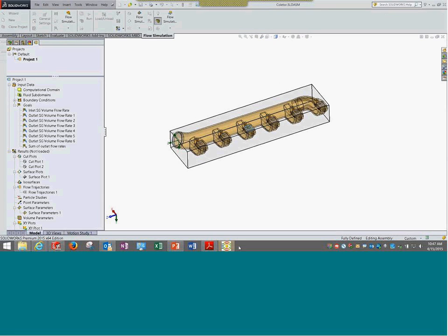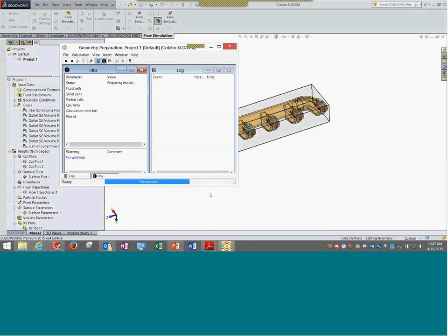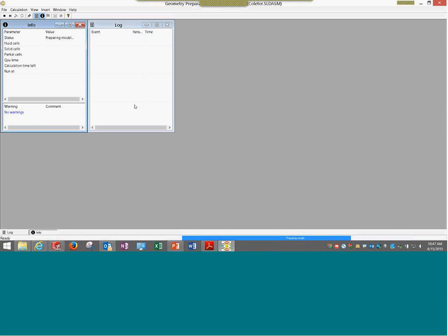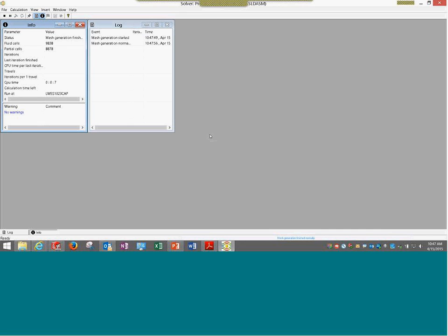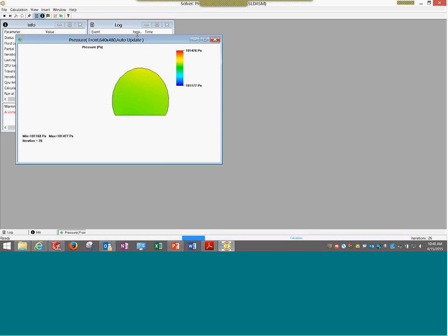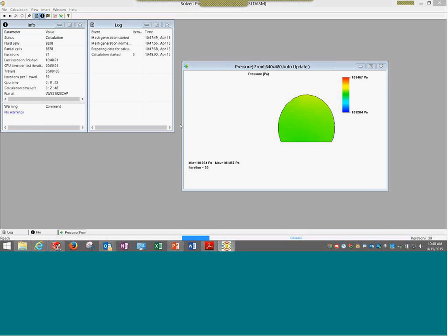It's an interesting thing. Unlike many software packages, and especially if you're comparing with Simulation, Flow Simulation allows you to monitor the results even while they are being solved. This is an interesting fact which can help you, because unlike Simulation where we trigger a solution, here we are talking more about something called convergence. So it may not be the final solution, it is in the process, and we can just see how it goes. We have this option at the top here, Insert Preview. While the solution is happening, we can visualize the result.